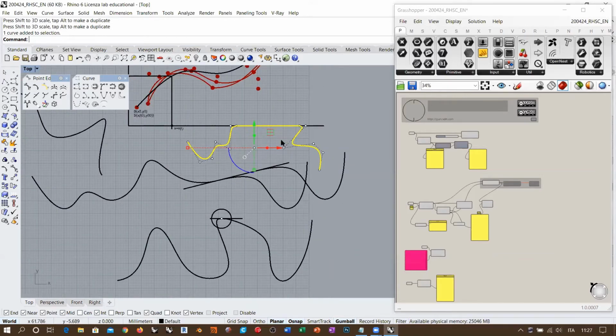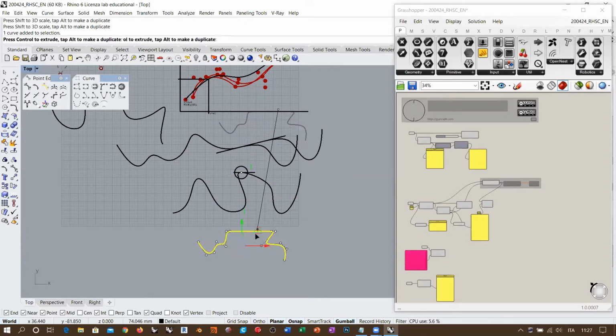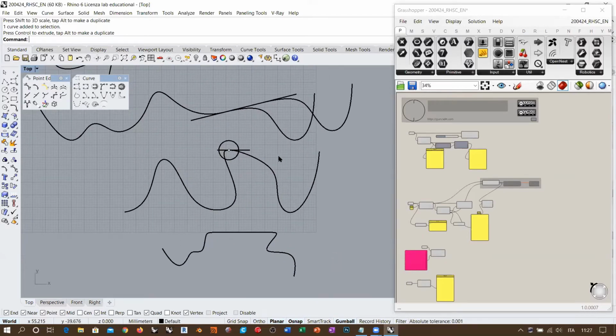Okay, now all that we are saying here, these are what I call the three basic rules for NURBS curve definition. So initial and final tangency, passage through a point or tangency along an internal point of our NURBS curve, and a flat portion of a NURBS curve. With these rules, you can basically create whatever type of condition that you might want to create.